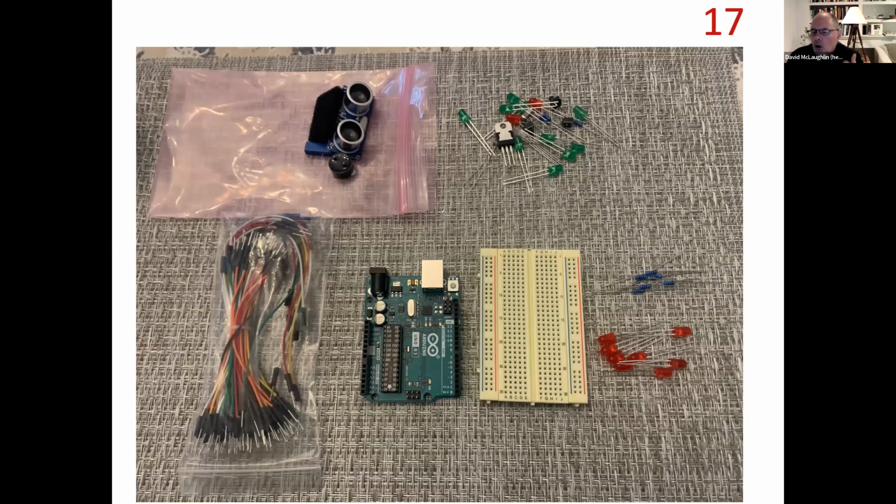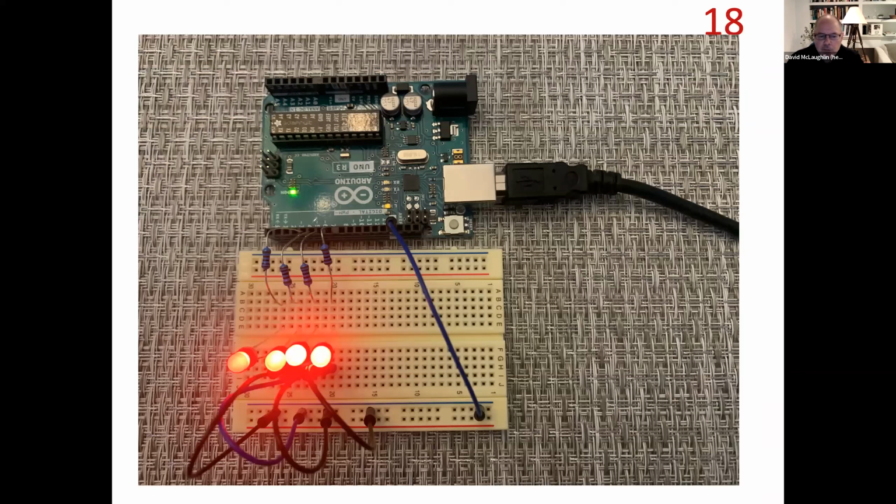Now, how are we going to know if this code is doing anything? What we did is we set some pins high and we set some pins low. I'm going to connect some LEDs to those pins. I'm going to show you a circuit here where it has 4 LEDs connected to those pins. I pulled the pieces that I need from the kit, and then I built them here. What I was doing is setting the upper nibble of port B, which corresponds to pins 4, 5, 6, and 7. I connected those with some resistors to some LEDs on the breadboard, and they're glowing. So that code just turns on those LEDs. It's not doing anything too special.